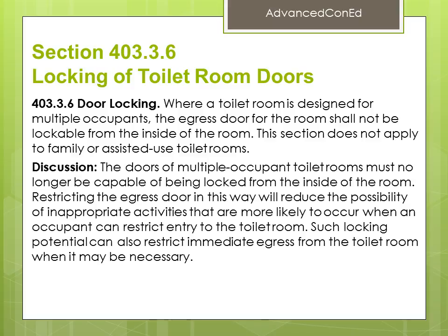Section 403.3.6 Locking of toilet room doors. 403.3.6 Door locking. Where a toilet room is designed for multiple occupants, the egress door for the room shall not be lockable from the inside of the room. This section does not apply to family or assisted use toilet rooms.